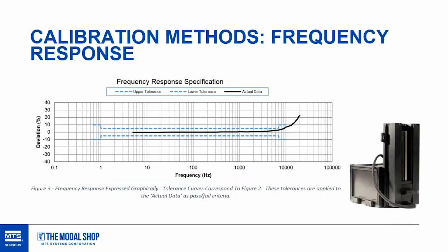They'll maybe get a high frequency and a low frequency. And it's usually defined by the calibration code. There'll be a specific call out for the frequency range, and you can elect to get a low frequency. On the other hand, there's people who really don't mess with data below 20 hertz, for example. They're dealing with higher frequency modes, they're testing smaller objects, and they might only be interested in what happens to that accelerometer in the high frequency range, which is a lot of our customers. So in those cases, oftentimes just a high frequency calibration will get you what you need for frequency response.